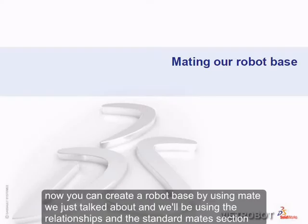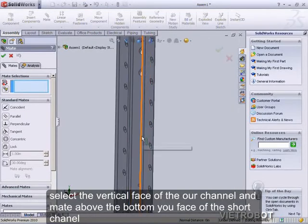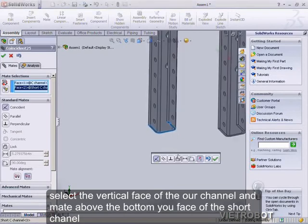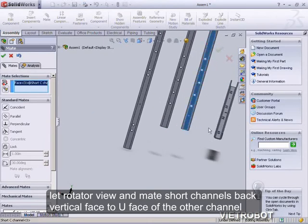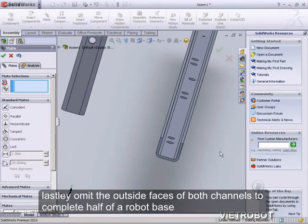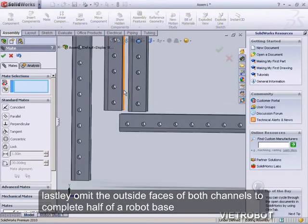Now we can create our robot base by using the mates we have just talked about, and we'll be using the relationships in the Standard Mates section. In the Entities to Mate box, select the vertical face of the outer channel and mate it with the bottom U face of the short channel. Then let's rotate our view and mate the short channel's back vertical face and the U face of the outer channel. Lastly, we'll mate the outside faces of both channels to complete half of our robot base.